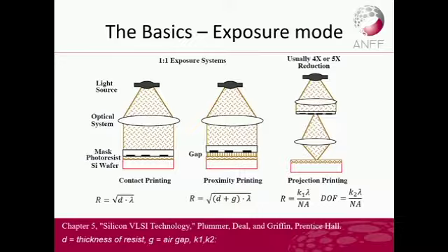What I forgot to cover is that your resolution actually depends on the wavelength of light, based on the diffraction limit of your light. So if you need to achieve 20 nanometer using contact lithography, probably the only method is either extreme UV lithography or X-ray lithography.